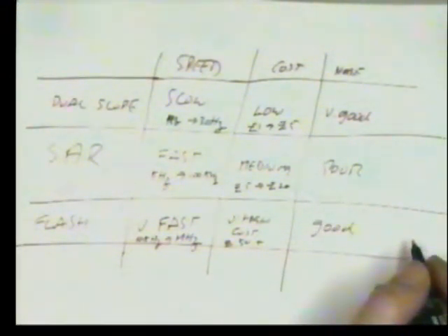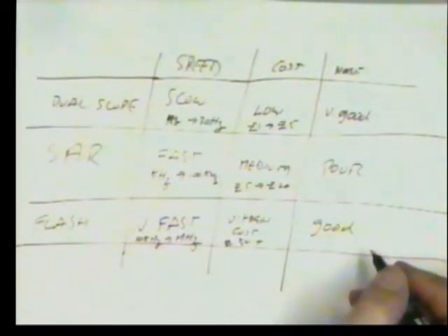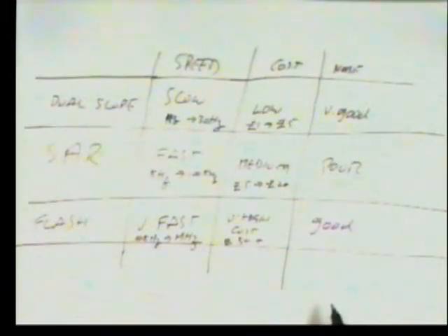The noise immunity, surprisingly enough, is good. The reason they're good is that the flash ADC is going to go faster than the noise. So all that will happen is it won't disturb the answer. You'll actually convert the noise, and you'll get it as a real number reading in your data stream.